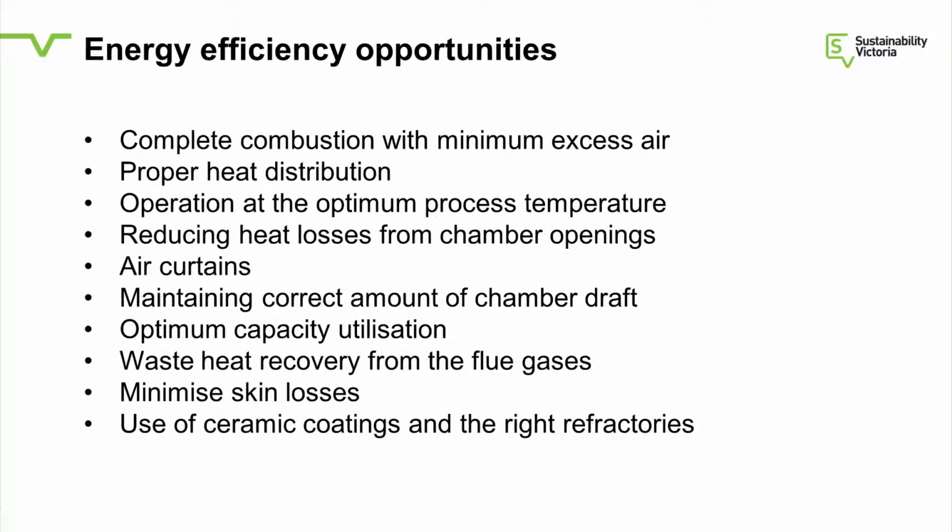Skin losses: again, the same thing applies at higher temperatures. Higher levels of insulation are needed. Certainly the use of better coatings, like ceramic coatings, and better refractories to reduce the losses is becoming very popular with higher temperature processes.